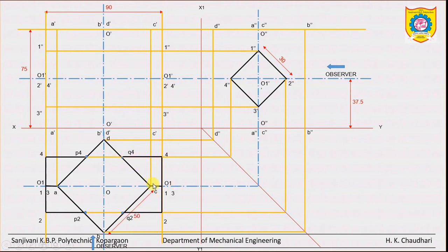Then the middle portion of this prism: due to this vertical prism, we can't observe these middle edges, but as they are there, draw the hidden lines, these 3 hidden lines. Now see, we have completed the top view.